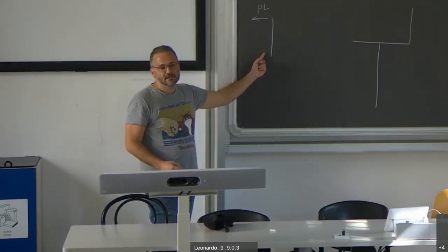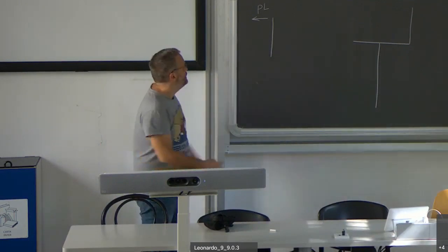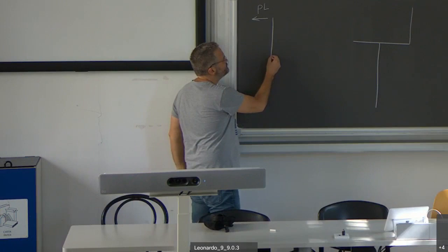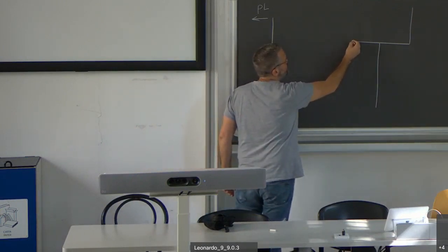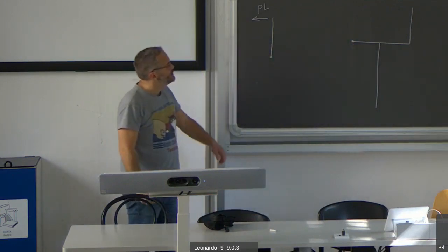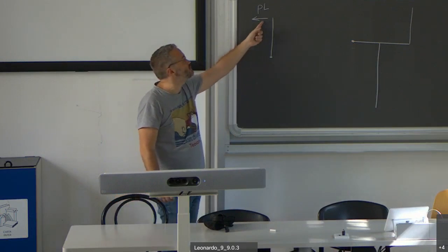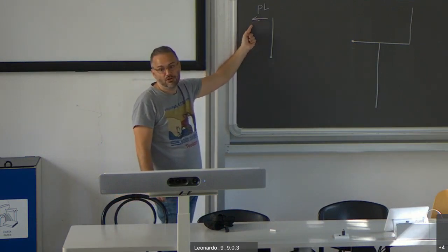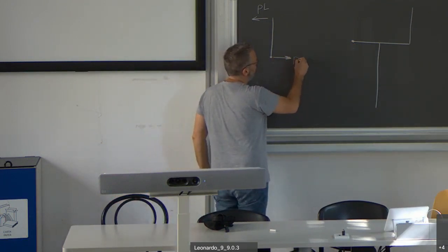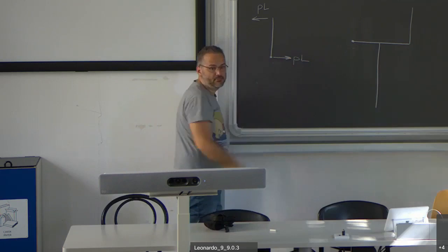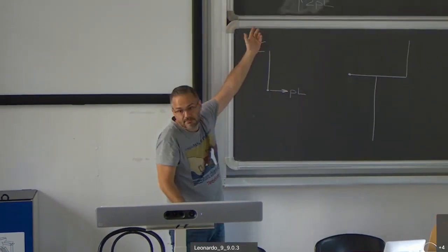How does this stay in equilibrium? Well, it is connected with the structure by a point which is here and here. The only possible way to have this portion in equilibrium, since it is subjected to a horizontal force which points to the left, is to have a force which points to the right here at the bottom, because all the other points are free from loads.